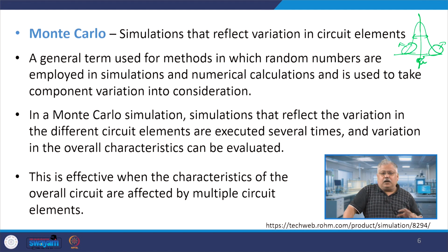And in Monte Carlo simulations, the simulations that reflect the variation in different circuit elements are executed multiple number of times, and then the overall variation in the characteristics is evaluated. So Monte Carlo obviously takes a larger amount of time because the simulation time is larger, but it also uses a large amount of CPU resources in order to do it, right. And the time for convergence in Monte Carlo is also very large.